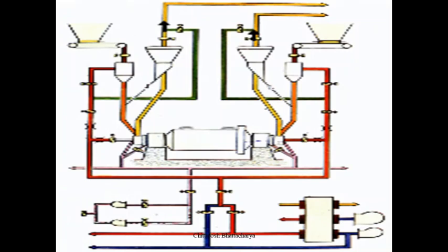For ball tube mill, we find that a cold PA, pressurized PA system is used, and from there hot primary air and cold primary air is mixed, and that air is fed to the pulverizer ball tube mill. Along with that, we have hot air supply to the coal feeder inlet, so that there is sufficient pressure in the feeding line.